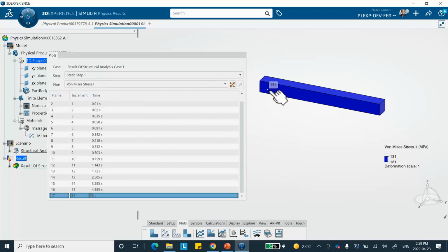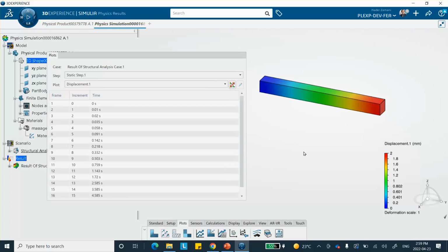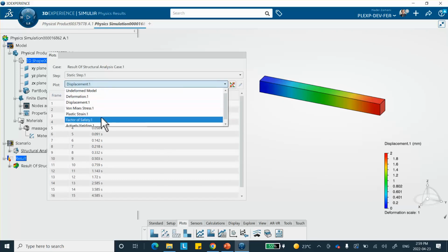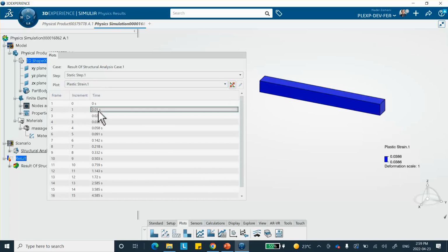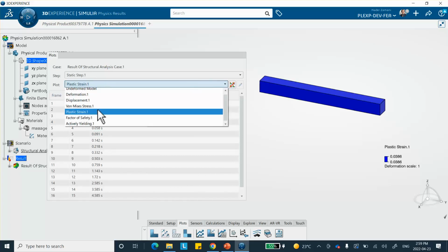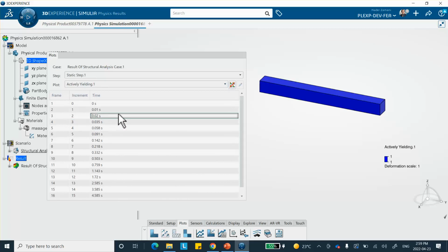Now, if you go to displacement, on the other hand, there we are. You can say 2 millimeter displacement over a 5-second interval. This is not real seconds, real time, but you can also plot other stuff such as, for example, let's see, plastic strain. So uniform plastic strain, we know that, but nothing surprising about that. Let's see now. So everything has yielded. We already know that.